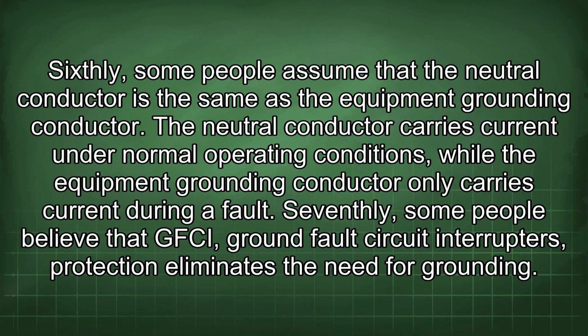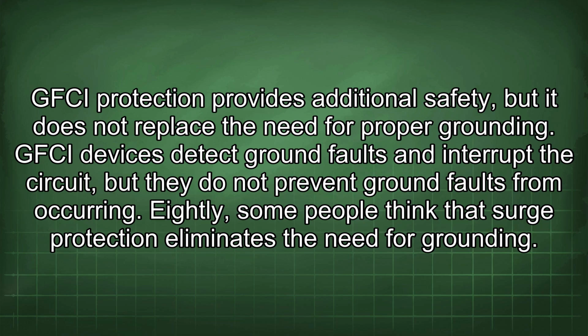Seventhly, some people believe that GFCI, ground fault circuit interrupters, protection eliminates the need for grounding. GFCI protection provides additional safety, but it does not replace the need for proper grounding. GFCI devices detect ground faults and interrupt the circuit, but they do not prevent ground faults from occurring.